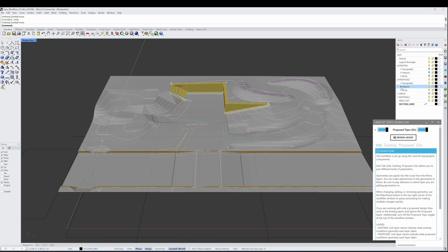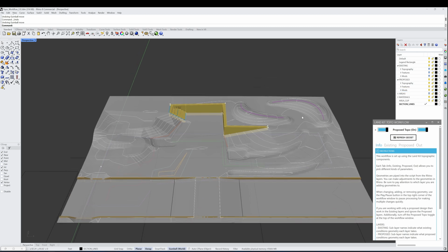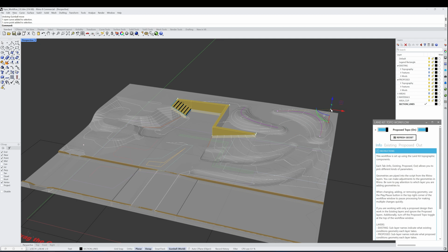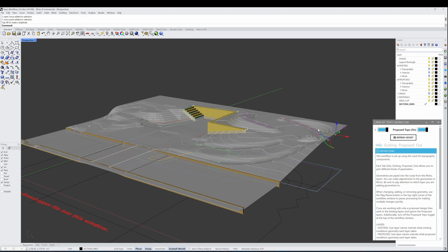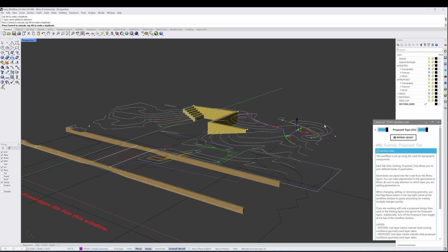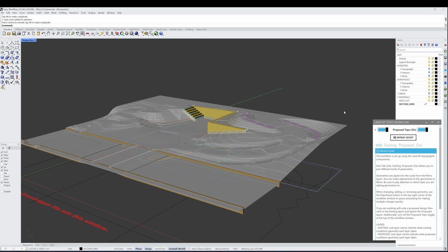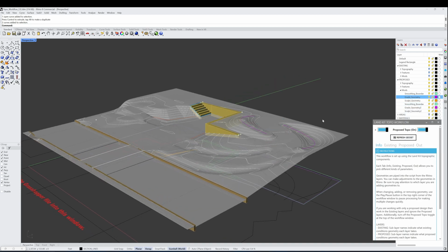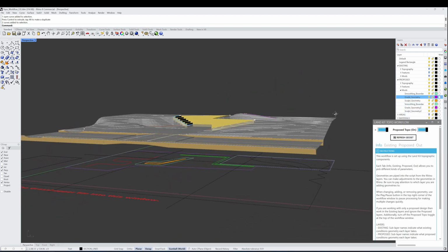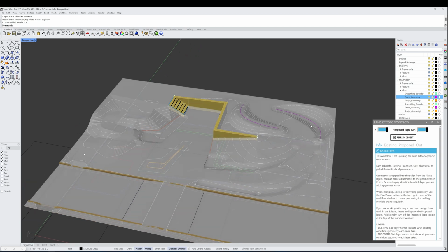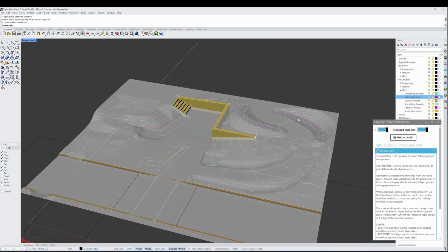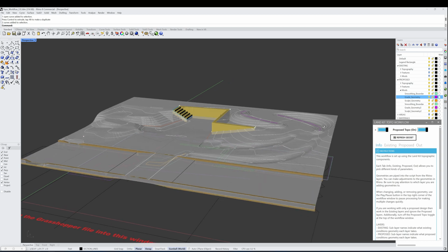Another thing you'll notice here is that we have layers specifically for features and mods. And features and mods will update automatically. You saw a little bit of that at the very beginning, where I was moving around these mounds, the curves that are creating the mounds. In this case, this is a mod that allows us to create a mound using a 3D object, which is called the grading tools. So if I open this up in the mod, you'll see we have some graded geometry here, and that's these two curves that we're actually using three-dimensional geometry to create different types of forms in the landscape. So the updates are happening automatically for the mods and the features. You don't need to worry about hitting a refresh button for these.